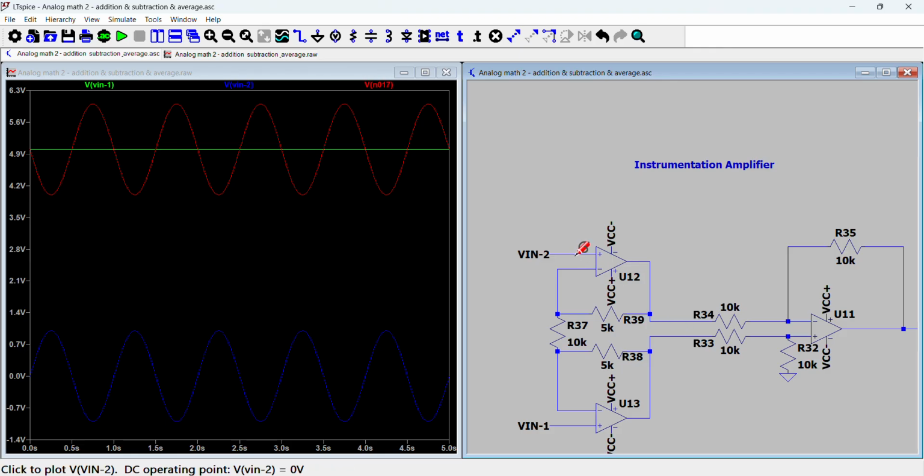Notice that this is the difference of the voltages that are being amplified. So we don't actually know what the voltage here and here is, right? It entirely depends on the inputs. But we know that the difference between the two is now multiplied by 2. And this circuit will measure that difference. So what we expect is the output is going to be this minus this times 2.